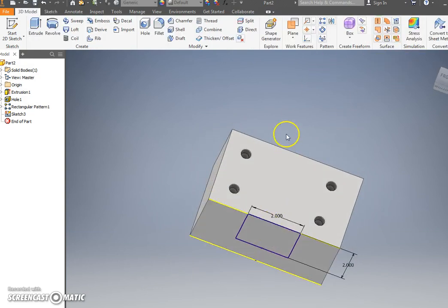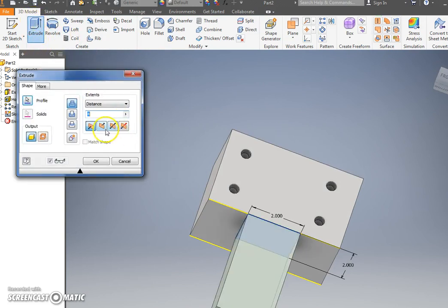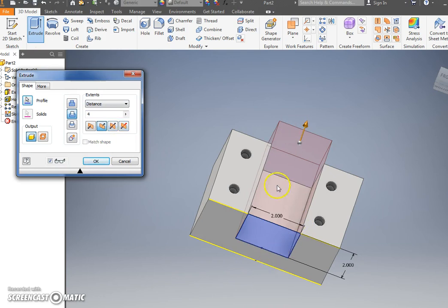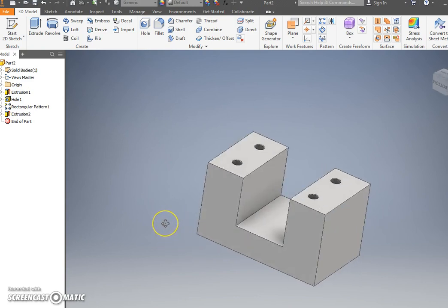We're going to cut this out now. So if you press extrude and you go through the object, it automatically defaults as cut. You can bring it back and eyeball it, whatever else. But if you go all the way through, that's fine. If you want to set it to the very end, you can set it to the 3 inches we did. I'm just going to push it all the way through just for now. There we go. Okay, so we're getting that done.